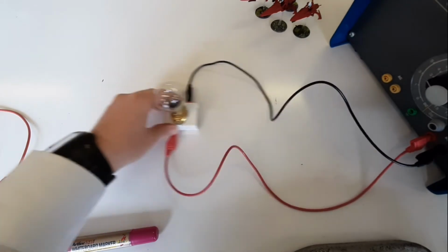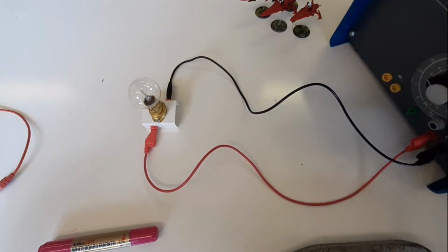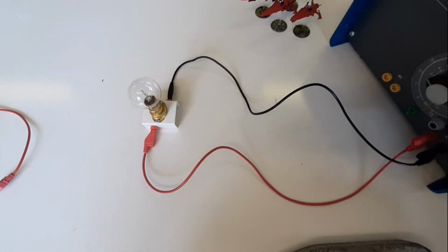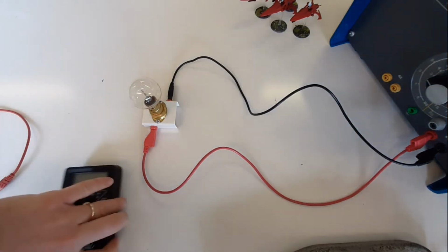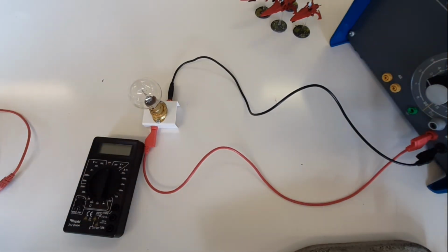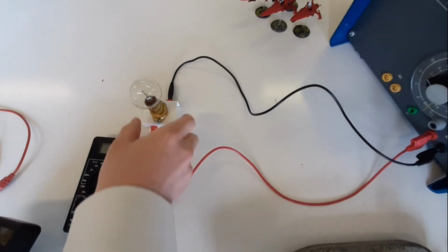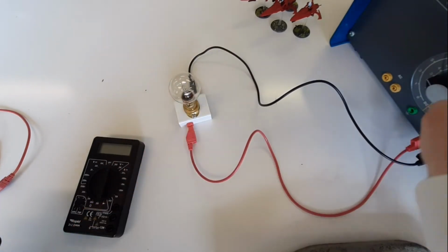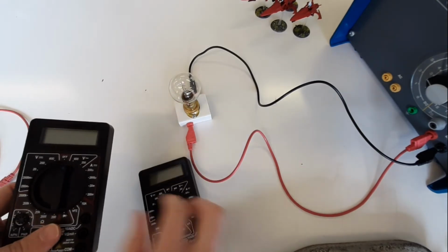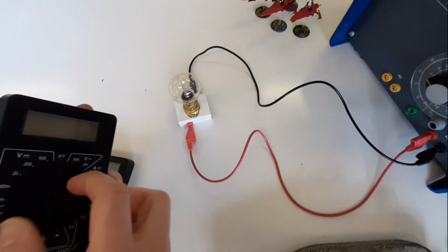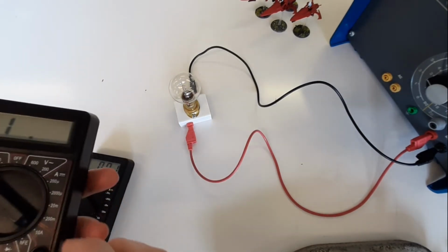Right, so this is the most important GCSE experiment you can do in circuitry. And it's really straightforward. You should remember it. It's going to get you those 3 more or less guaranteed marks. And for it, you need to have something to measure the resistance of, some sort of power source, and 2 multimeters. One set to voltmeter mode and one set to ammeter mode.